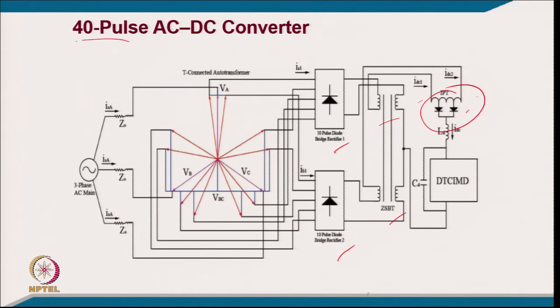In this case we are using the multi-phase concept to convert 3 phase to 2 sets of 5 phase, then we are using phase staggering so that we get the phase shift. So, the pulse duration will be 360 by 40, and that is the same angle by which we do the phase staggering, and then we have a ripple injection or pulse doubling here. In diode we can do pulse doubling, but of course if it were a controlled converter with a thyristor, you could have increased the number of pulses, not only double but 3 times, 4 times, which we discussed in the last lecture.